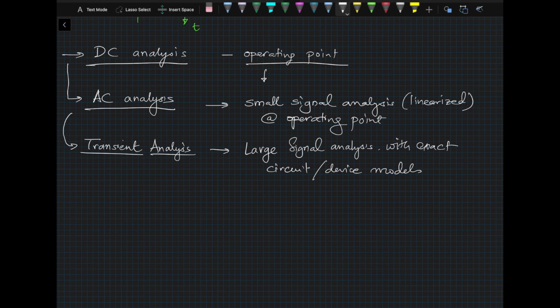However, transient analysis is the so-called golden truth, because that's where you are satisfying all the equations. If somebody only gives you DC analysis and AC analysis, then, yeah, whatever. But once they show you transient analysis, I think those results are believable, assuming they have put together the circuit correctly. Okay. All right.